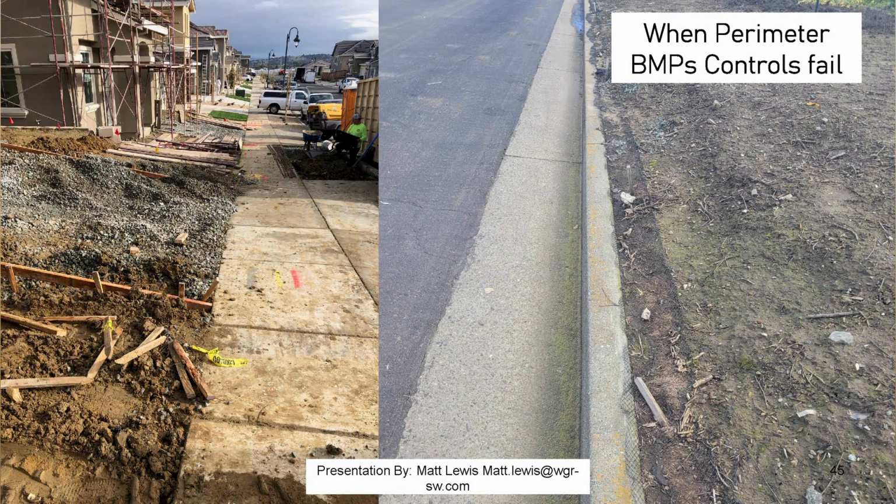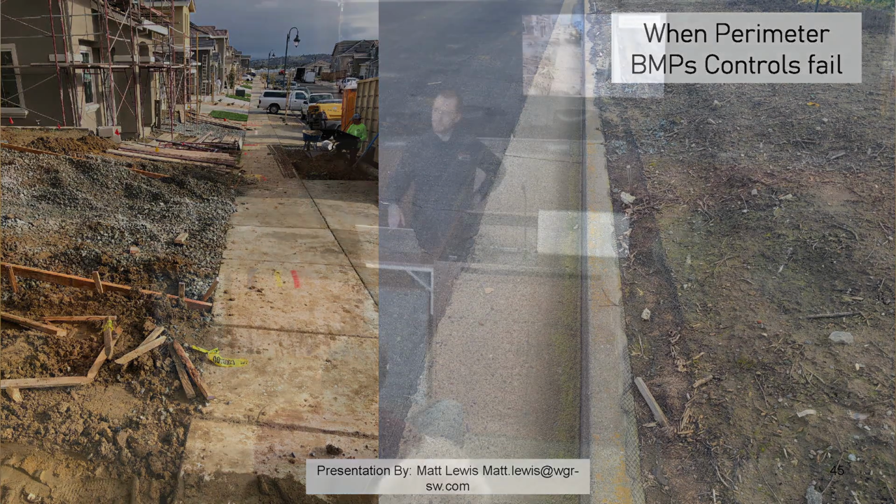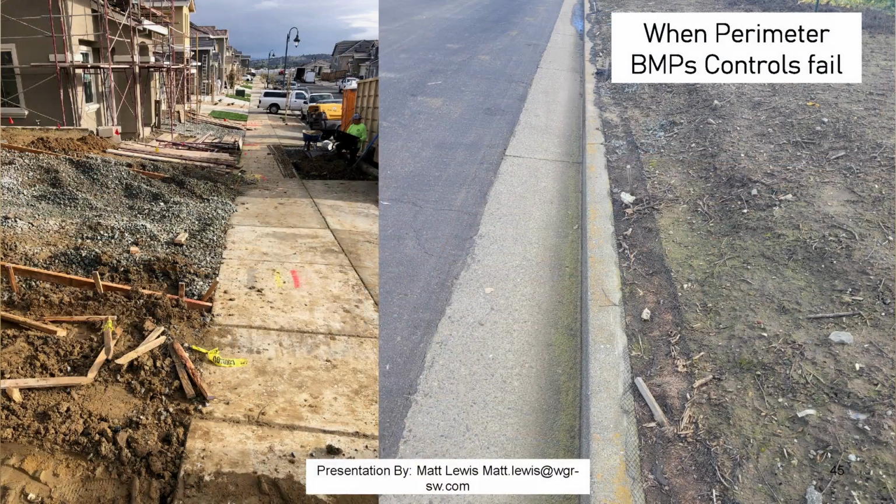All right, so now we'll get into when BMP controls fail. So on the right, this is actually a site of mine that I have been trying to tell them for over a year that their fiber roll is a mess, it's all squished, but they've got that curb cut back there. And so I'm like, hey, you guys, just come in here and clean up this curb and you won't have to put the fiber roll down. Now, of course, they never listen to me and they just come in and put fiber roll down. I don't know if they're writing it off or what they're doing, but here's a perfect example of a totally flattened out fiber roll where they could just deepen that curb cut back and save themselves some money.